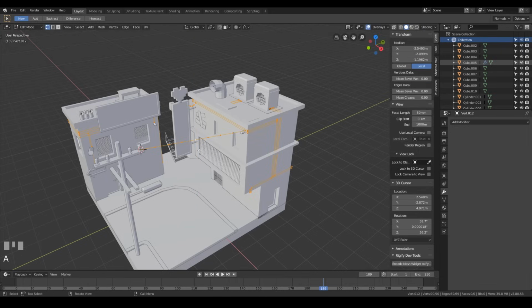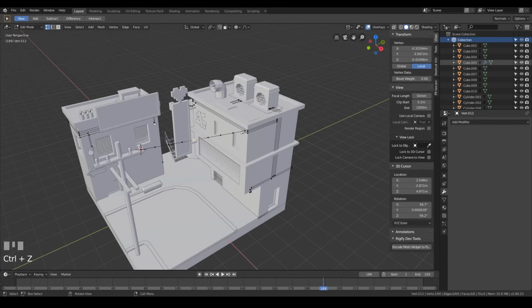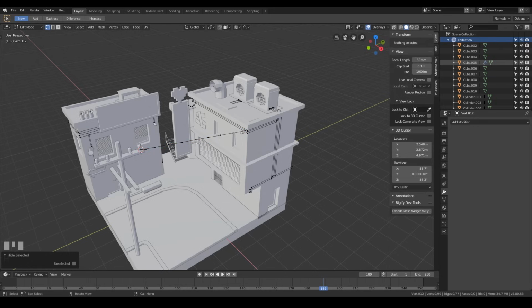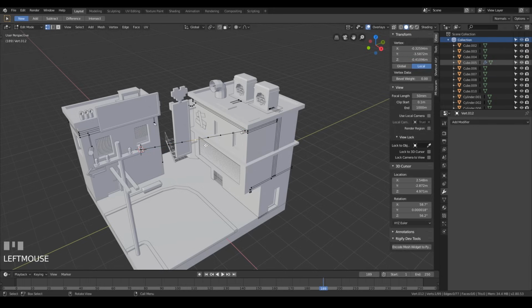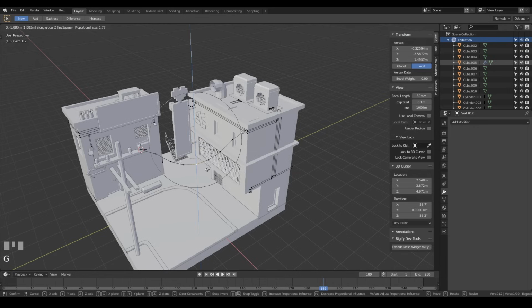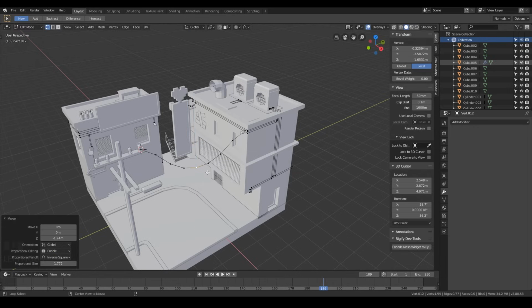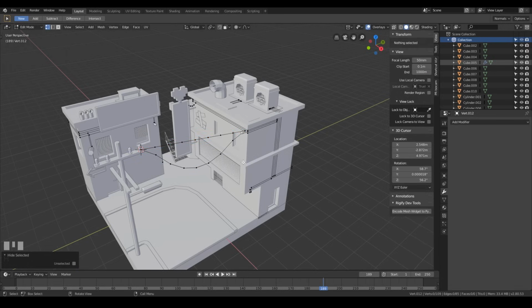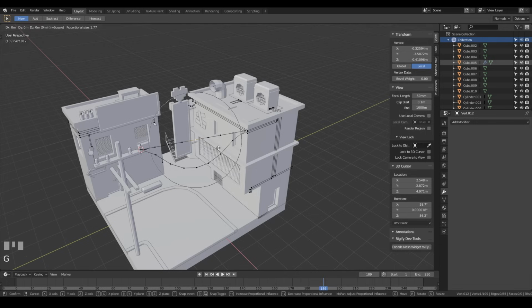Okay, but first let's just select it, duplicate it, press H to hide, and now select this, move it, and now if you press Alt H, the original is unaffected. You can duplicate it again, hide, select this one, grab, and move it along.